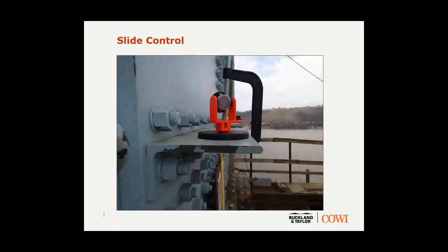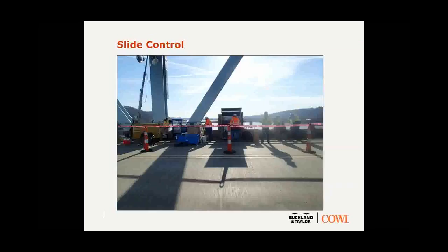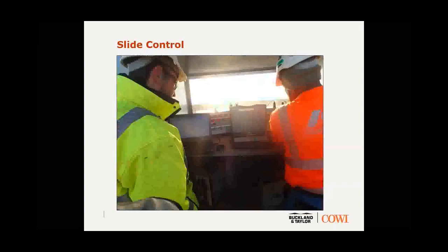VSL from Switzerland, who ran the slide as well as the earlier span lifts for Walsh, had a system of laser targeting fed into a processor. Charlie will probably talk about it a bit more. That controlled the longitudinal locations of each of the 5 pulling points. And then all of that slide was controlled from a little booth on the bridge. Guys went along for the ride, basically with information fed into a laptop and controlled from a very simple panel.